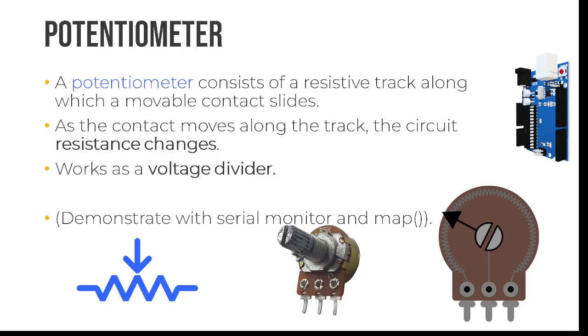And if I move the wiper and I measure again, 10K, right? Because this is always fixed, right? This terminal is called the wiper, right? Moving across that. Imagine that the wiper is right here, okay? What will be the resistance if I measure here?